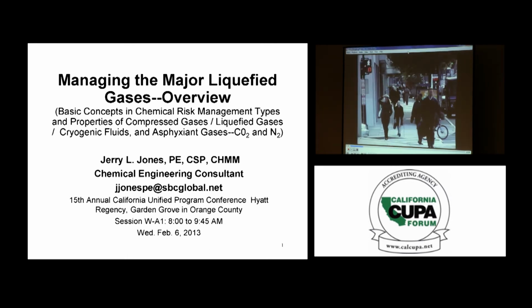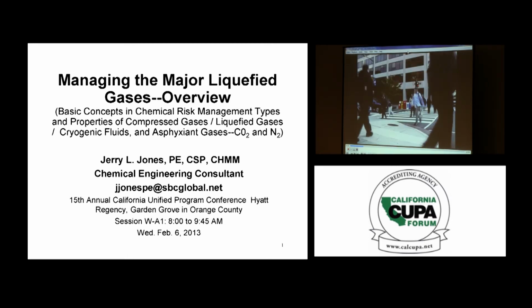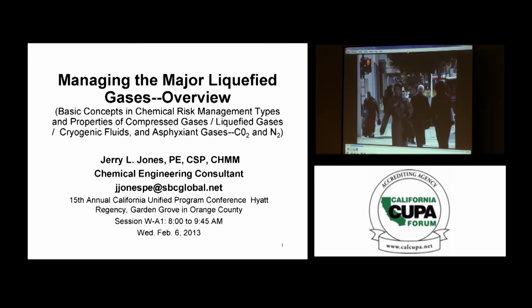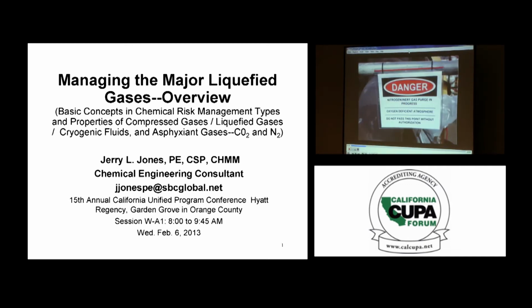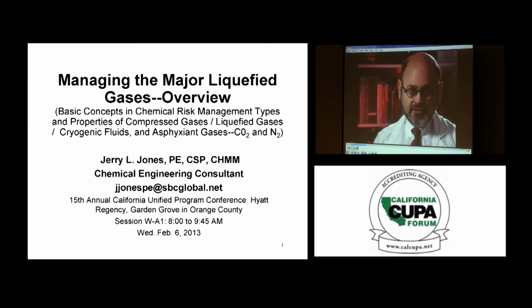Oxygen comprises 21% of the air we breathe, and humans cannot survive for long when it drops below about 19%. In refineries and chemical plants, dangerous, low-oxygen environments are created when inert gases like nitrogen are used to remove oxygen from pipes and equipment. The risk of an oxygen-deprived atmosphere is that you'll get trapped in that situation. You'll get trapped and die.